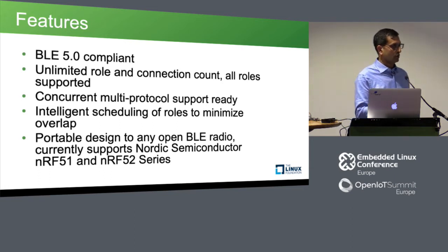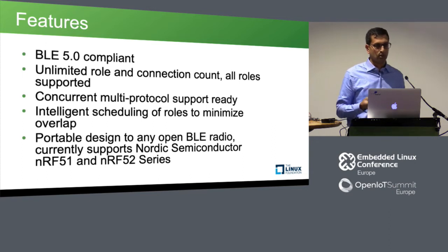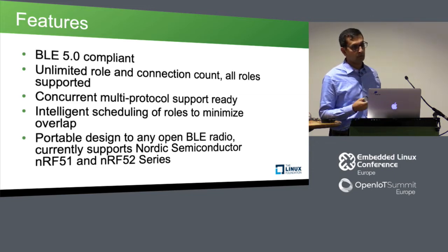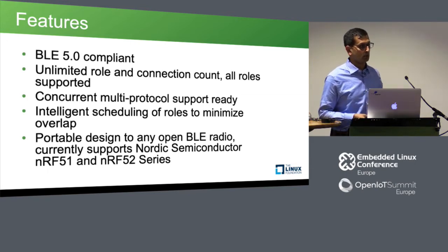And also as a slave, if a single device is a slave to more than two masters, since the slaves depend on the master clock and they would drift into each other, the current implementation on the upstream master is able to detect that and then do an auto connection update to move them to non-overlapping intervals.